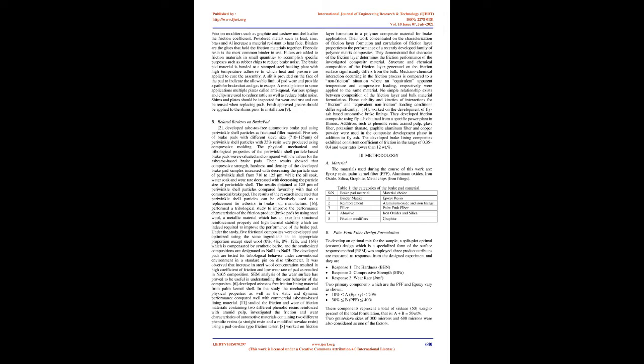Phenolic resin is the most common binder in use. Fillers are added to friction materials in small quantities to accomplish specific purposes, such as rubber chips to reduce brake noise. The brake pad material is bonded to a stamped steel backing plate with high temperature adhesive, to which heat and pressure are applied to cure the assembly.